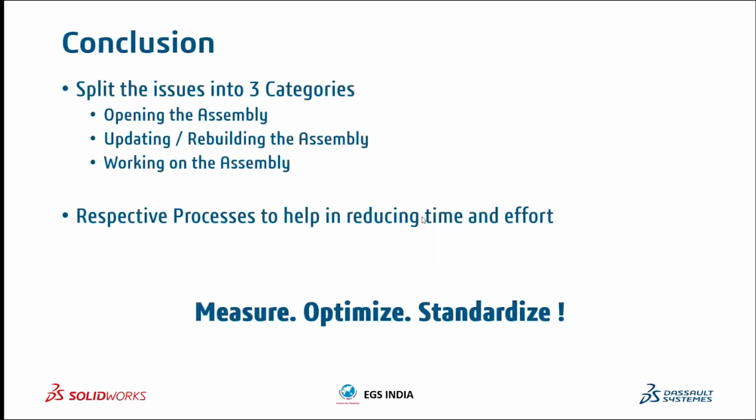So what we've basically done is to handle large assemblies. Efficiency is not just about having better hardware, but about how we manage our structure data. By identifying where the issue occurs, whether it's during opening, rebuilding, or working, you can apply the right optimizations. Simple practices like reducing unnecessary detail, controlling dependencies, and using the right tools can make a significant difference. Implement these techniques in your daily workflow and create standardized practices for large assembly handling across your team. Measure, optimize, standardize. Thank you.